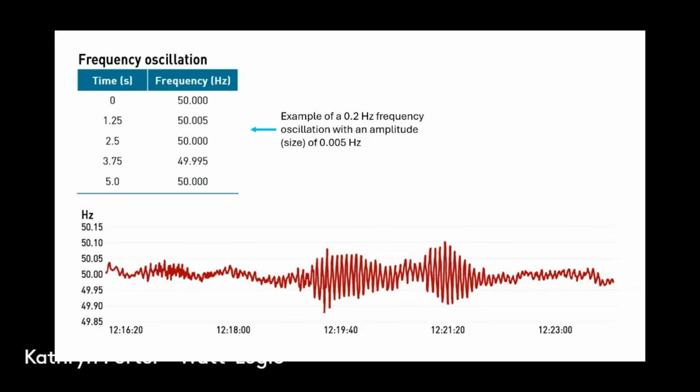Then you had interconnection tripping, so that caused the Iberian grid to be islanded, so isolated from both Europe and Morocco. Then after that happened, you had more gas, nuclear and hydro generators tripping off. The grid frequency fell far below the levels at which equipment was able to operate. Voltage fell to zero and there was a full system blackout.